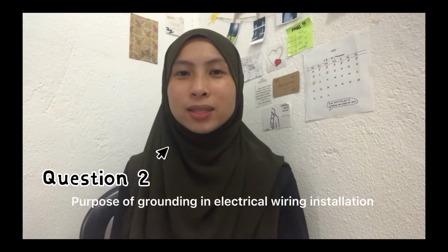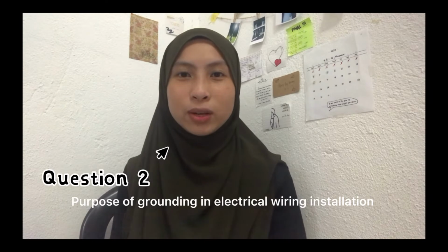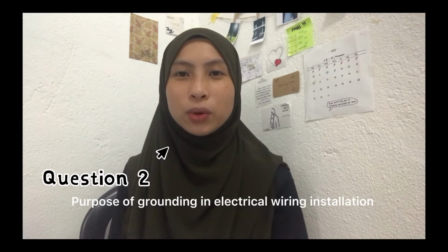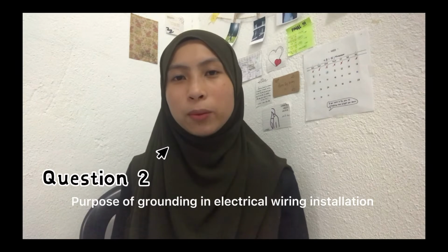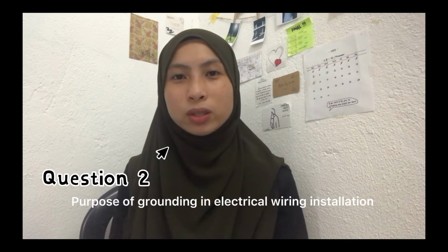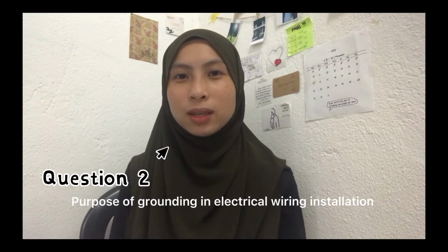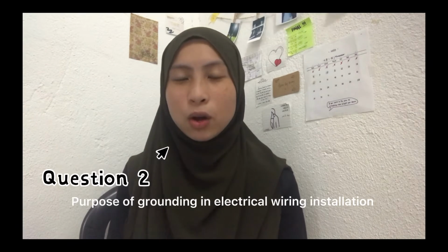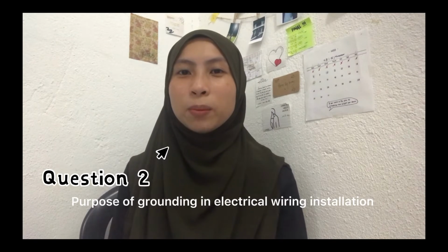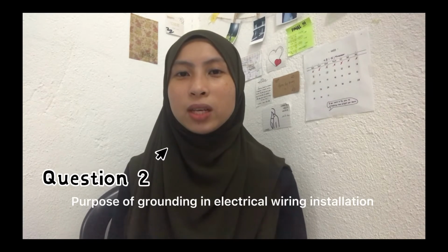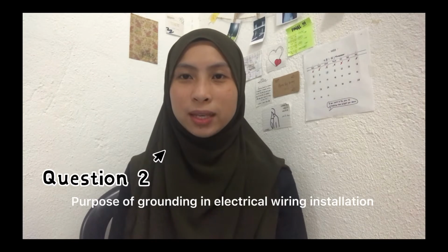Next question, discuss the purpose of grounding in electrical wiring installation. The grounding wire takes the electricity that has built up during the malfunction and sends it outside of your home back into the ground. The grounding wire is typically connected to either a metal in the internal structure within the appliance or on the external housing. When the malfunction happens, rather than having the energy built up in the circuit, it flows back to the ground and turns off the circuit.